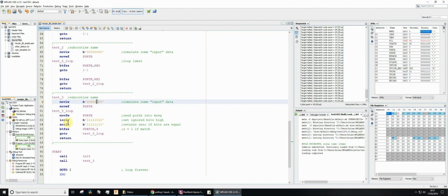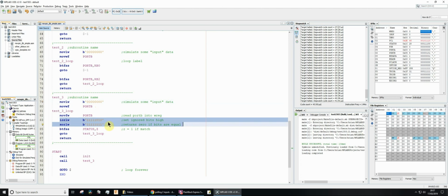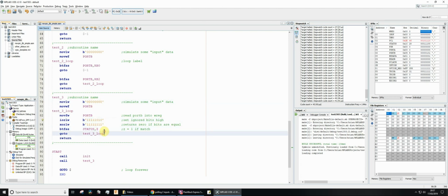And these two lines are the most important part, or fairly critical to understand. Anyway, everything is important, but this bit pattern defines which bits I need to look at on the input. Now, bits I'm not interested in testing, I set to ones. Remember, I'm only interested in these two.